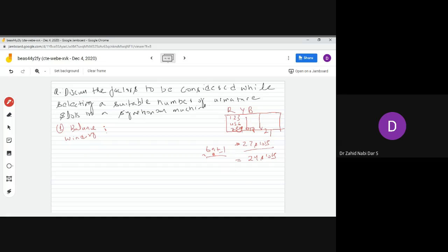In case of the induction motor, you saw a phenomenon of crawling existing because of the seventh harmonic, which is again an odd harmonic. Similarly, when you are constructing an induction machine, you should make sure that the windings are balanced. There are many unbalanced windings. Your two phases are balanced, but the third phase is unbalanced.